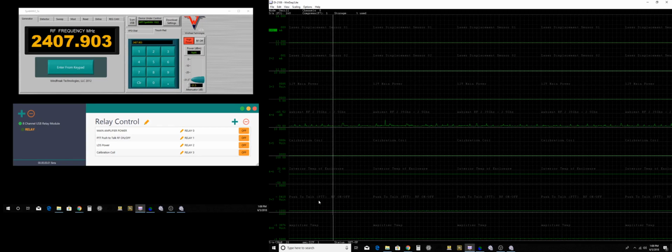Channel 7 is the push-to-talk, PTT. That's basically RF on, RF off. The amplifier, I think, is based on some kind of CB radio, and so in order to talk, you push to talk. You'll see it floats high when everything is turned on, and it has to be pulled low, grounded, in order for it to work. So that's how push to talk works.